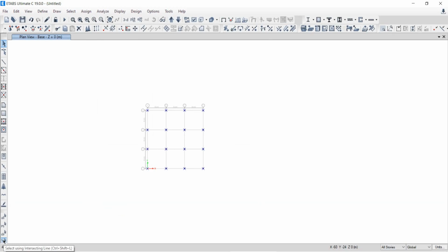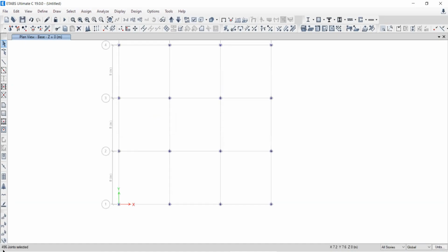That is why I told you earlier, when you are practicing with ETABS software, your concentration should always be on the right bottom and left bottom. Here it shows 496. If you look at this, you can catch the problem, something is wrong. If you come to this side, you will get the actual problem. First your concentration will come here. Our intention is 16, and we are getting 496. Something is wrong, so then I look at this side. Yes, that is the problem.